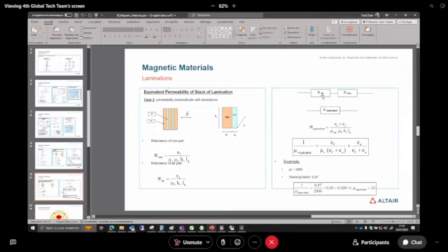So instead of having two reluctances in parallel, I will add a reluctance to the magnetic field. And then in the same example where I start with 2000, the 2000 becomes something like 33. This is really something we have to avoid doing for the lamination.